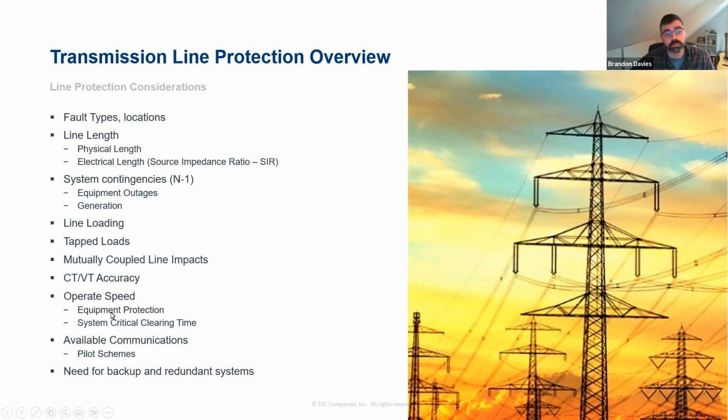And then with the operate speed, we also have to make sure we're clearing things fast enough to protect the equipment itself. And that's probably a little bit less of a concern at the transmission level, because everything has to clear so fast for the stability considerations that you're usually less concerned about the equipment thermal capacities than you are about the critical clearing time of the system for stability reasons.